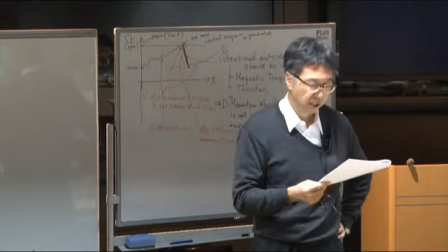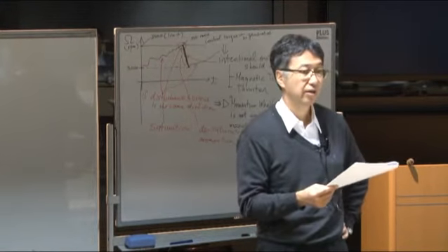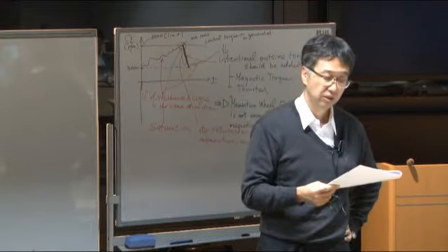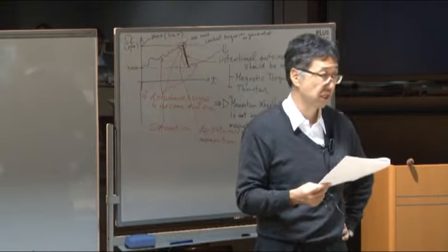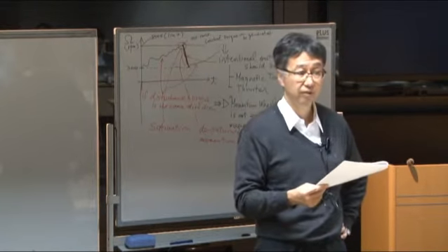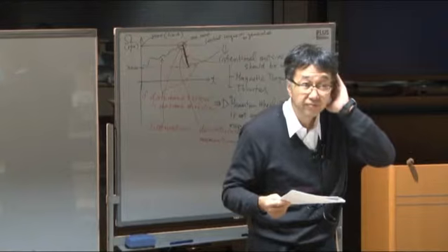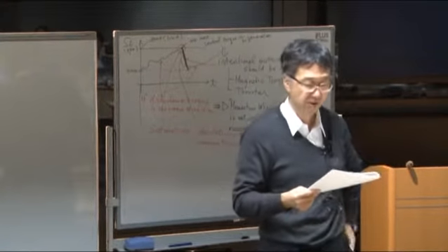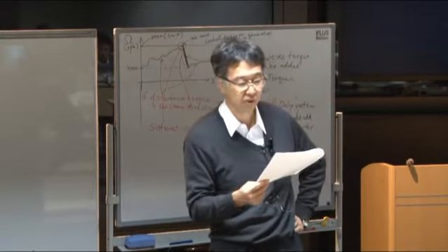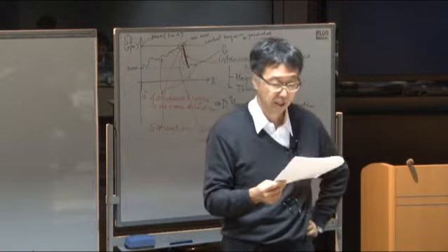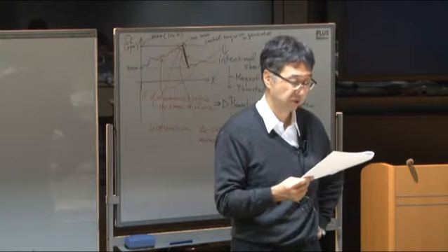But in this case, you have a fourth reaction wheel that is called an intermediate reaction wheel. Why do you have the fourth one? Only three are enough to get the control torque around the three axes. But why do we have the fourth one? We can repair this if something happened. Yes, so this is called redundancy. If something happens or some wheel fails, then the fourth one can provide some control torque around that axis.